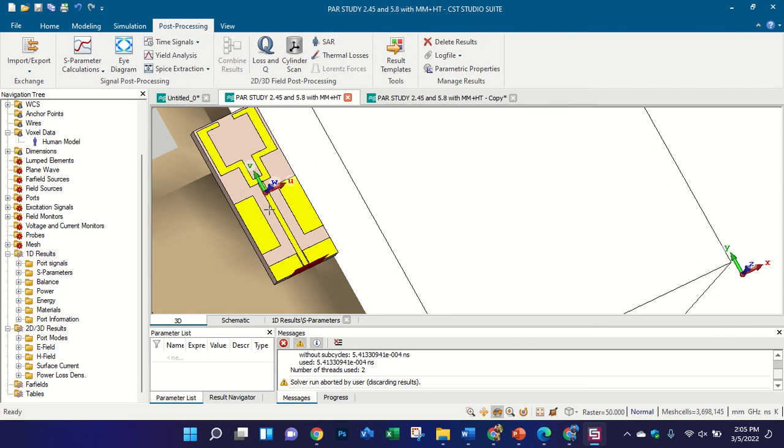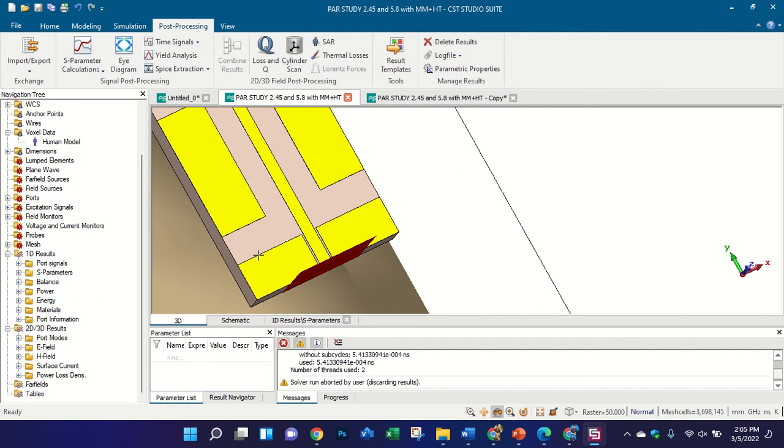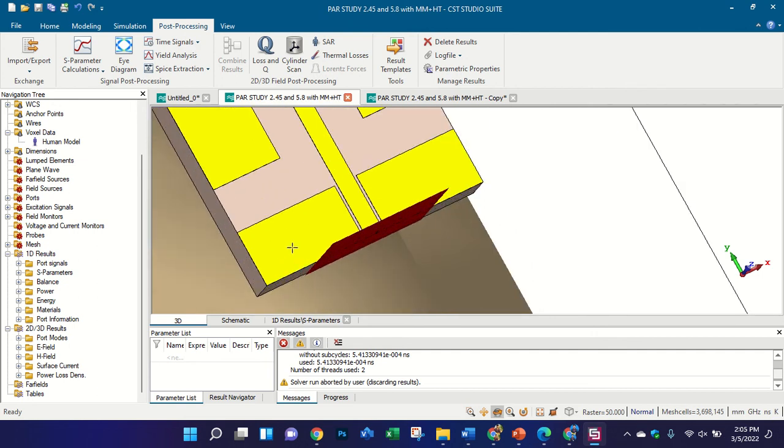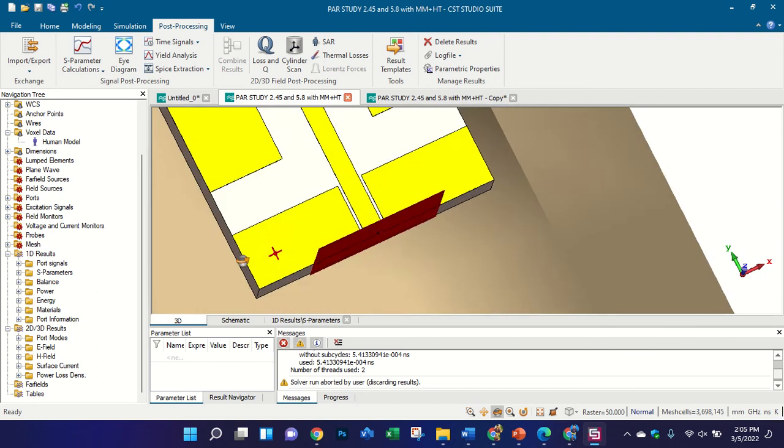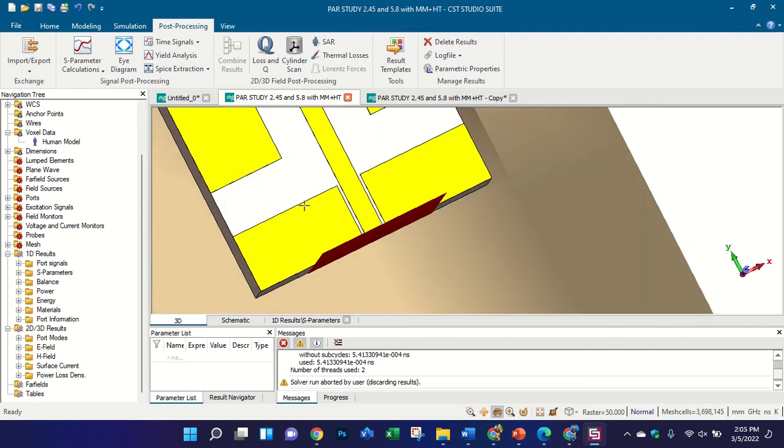Okay, and there are so many benefits of the CPW. The first one is that it helps you keep the size of the antenna compact, because the size of the antenna mostly depends on the length and width of the CPW. Also you can vary the frequency very easily with this length or width. If you increase or decrease the length of the CPW, you can control your frequency. If you increase or decrease the width of the CPW, you can control the bandwidth. If you increase the gap, you will find more bandwidth. If you reduce the gap, it will become narrowband. Okay.